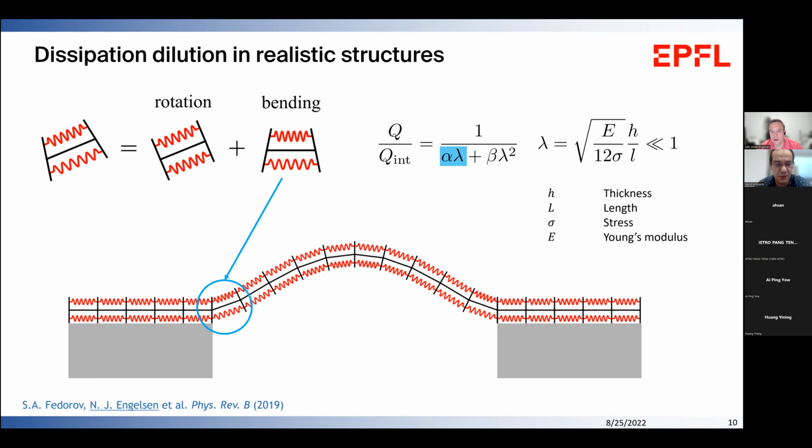Okay, starting with the first question. If you solve the Euler-Bernoulli equation for a uniform beam with a high aspect ratio, meaning it's very thin compared to its length, you can divide the beam into two domains: the distributed domain and the area near the clamping boundary. In the clamping boundary, the mode shape solution will be an exponential function to match the boundary condition at the clamping point, whereas the distributed mode is a sine wave.